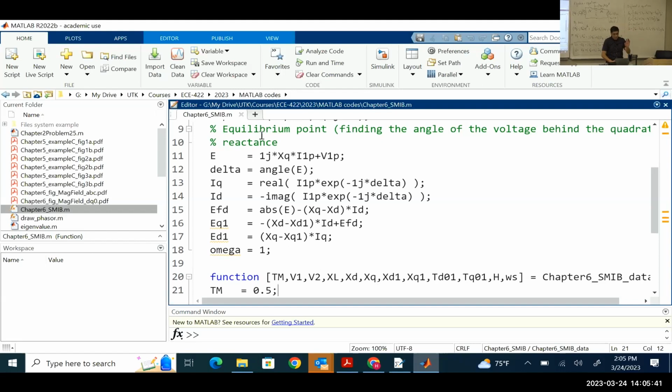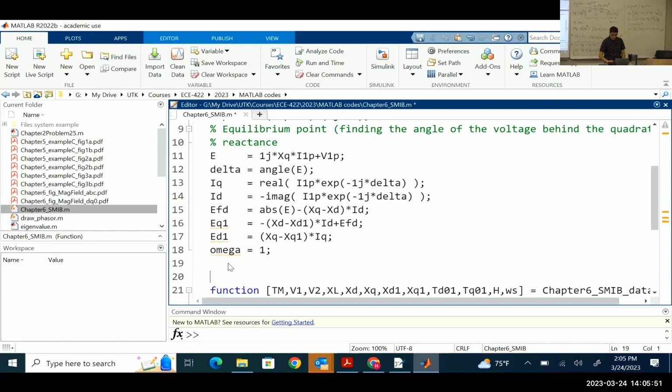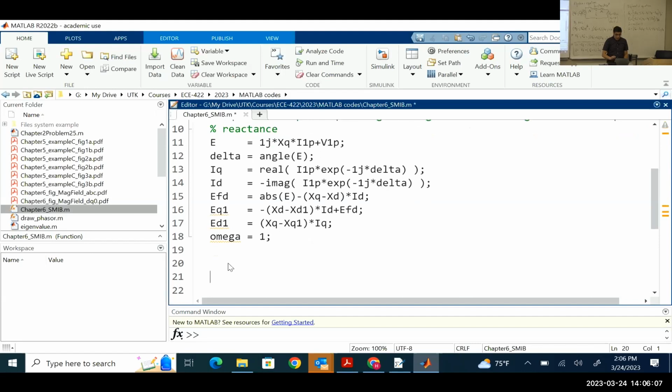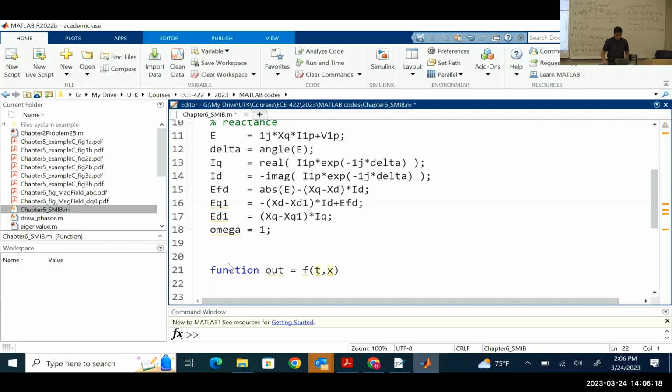Okay. So after this power flow calculation, we apply the steady state model and we get the equilibrium point of the machine. That's what we did. So what we need to do now, we need to simulate. We need to consider a short circuit, and then we need to consider the simulation when the fault is clear. First of all, because we need to use this in the simulation, let's define the variables for our system.